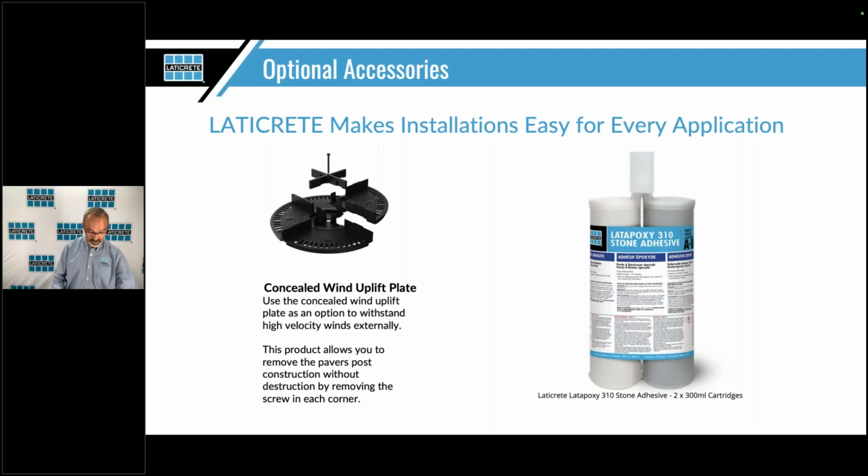Well, you can see in that breakout right there, if you remove this cross, this piece goes in there. If you remove this cross, those pieces are 4 individual pieces. You could take out 1, 2, 3, or all 4 of them, and put them back in there, drop them back into your system. They have a cross hatch they fit into. You drop that cross on top of it, drop the screw back into it, and the system's all back together. So even though you've epoxied it down, you still have the ability to take it out.